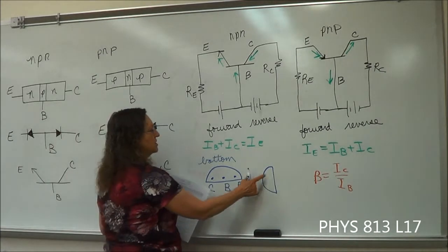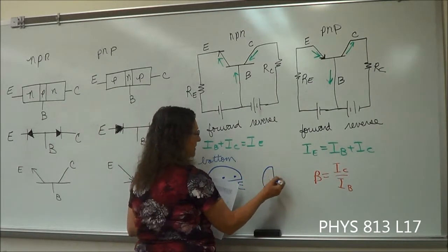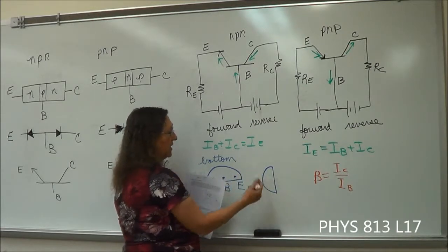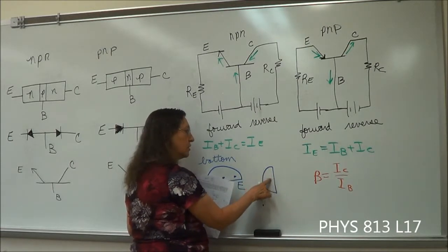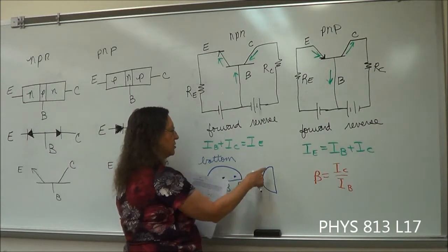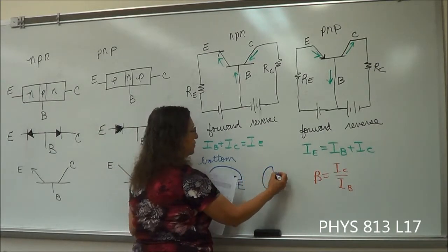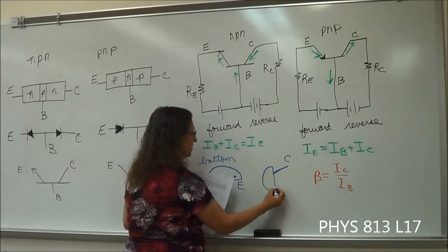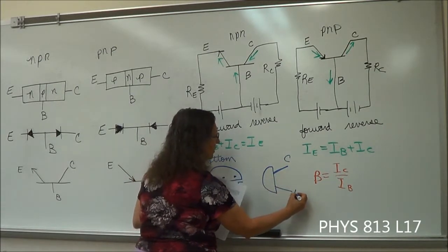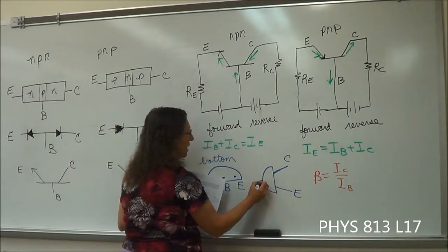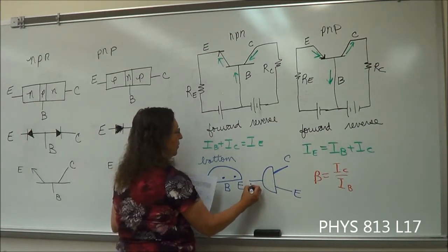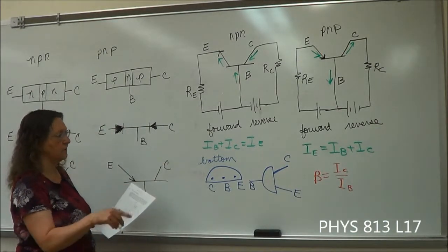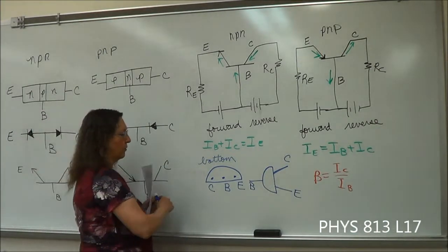circuit board. So if you're holding it like this, with the flat edge here, and the leads pointing away from you, I'm not going to draw dots here, because you don't see the dots. The leads will come out from behind. So this will be the collector, this one will be the emitter, and this one I'm going to draw over here will be the base. The middle one is the base, no matter what. It's just the emitter and the collector that you have to watch.